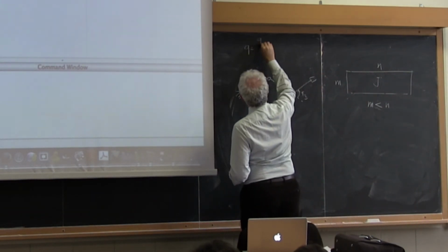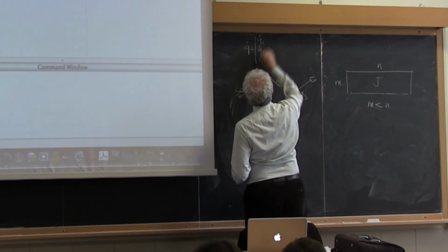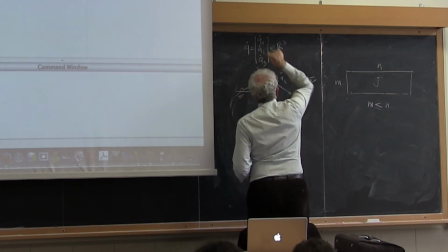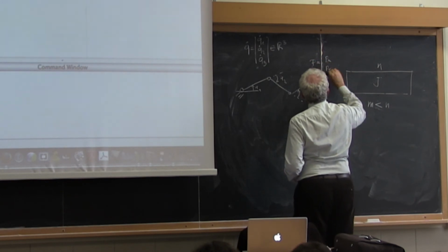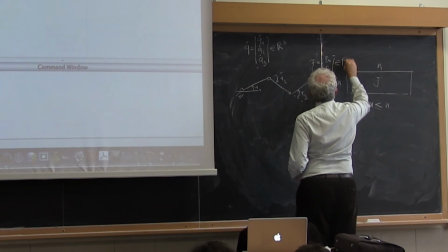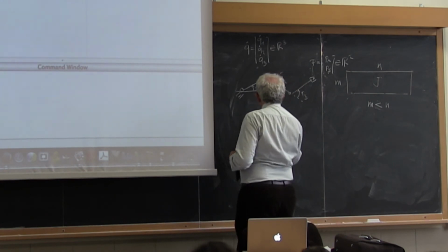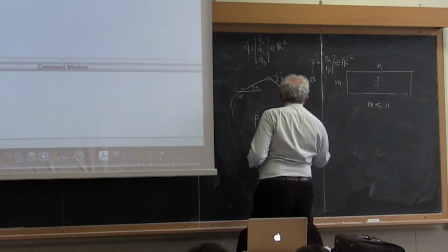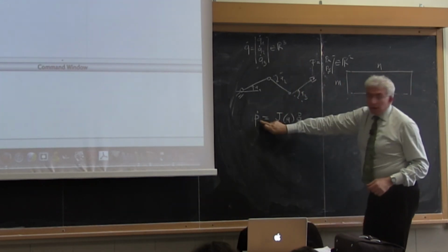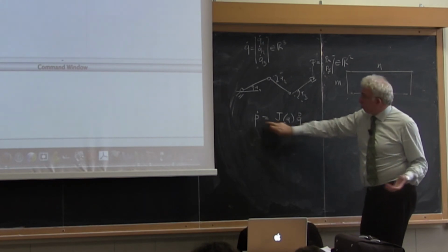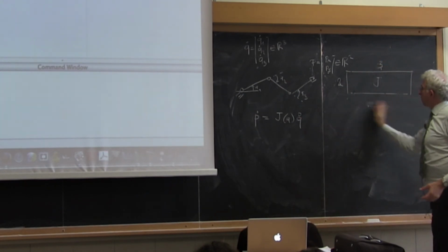Q is Q1, Q2, and Q3, and Q dot belongs to R3. Here I'm considering only P, which is Px, Py, in R2, in the plane. So when I compute the analytic Jacobian, which maps joint velocities in R3 to end effector linear velocity in R2, it has this form, a 2 by 3.